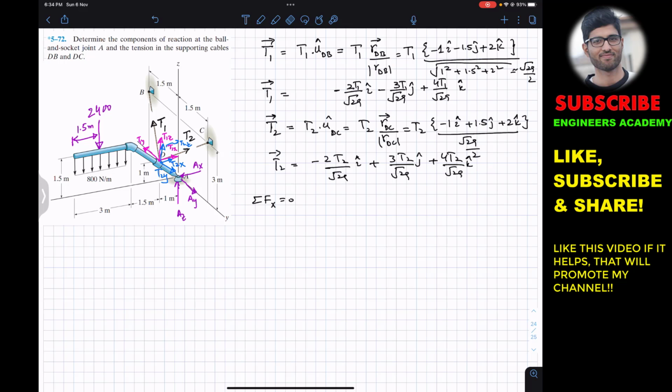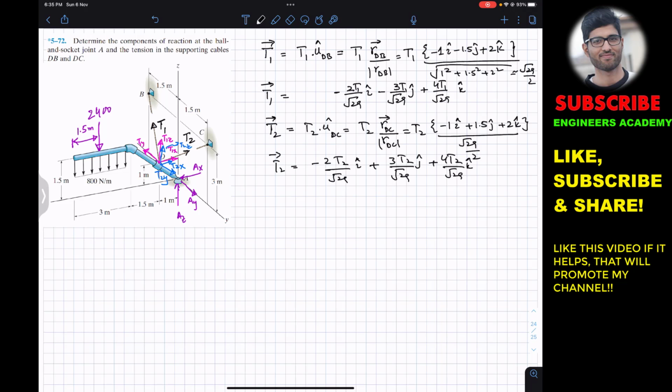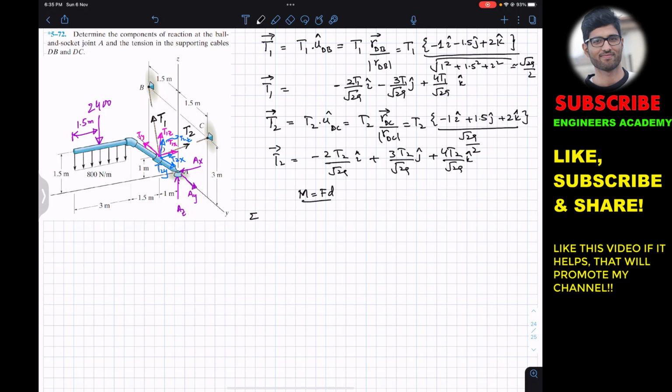Before going to apply the summation of forces along x, I am going to apply the summation of moment about the x-axis, that will be equal to 0, and I am going to apply the scalar approach for this problem. Since the scalar approach is more appropriate, this problem will be very easily solved if we find the moments by using the scalar equation that moment is equal to F times d. So we will apply the summation of moment about the x-axis equal to 0, since the majority of the forces or components are passing through that x-axis, and their moment arm from the x-axis is 0, so they are not going to produce the moment about the x-axis.